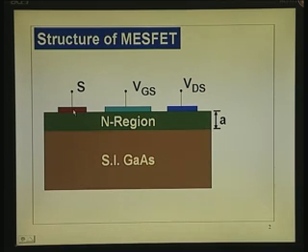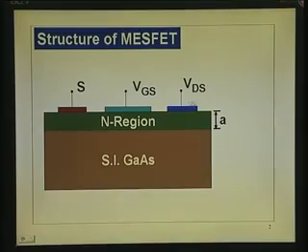Now, you have got here this region as the source, that is ohmic contact, and the drain, that is also ohmic contact. When you say it is ohmic contact, you understand what it is now. It is gold germanium alloyed onto that contact N-type region, that makes the ohmic contact. So, straight away evaporate gold germanium, alloy at 400 degree centigrade for about a minute, you get the ohmic contact. We will have occasion to get more into the technology details later, and this portion is actually the metal